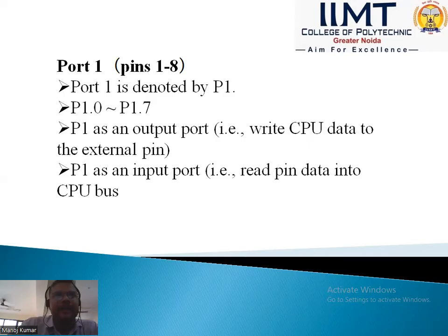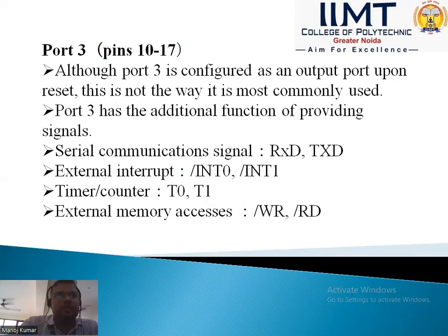Read pin data into CPU bus. Port 3. Port 3 pins are denoted by P3.0 to P3.7. All are input-output pins. Although port 3 is configured as an output port upon reset, this is not the way it is most commonly